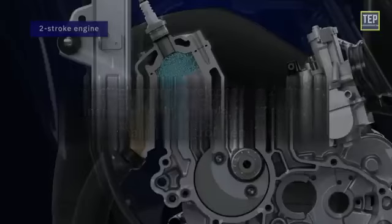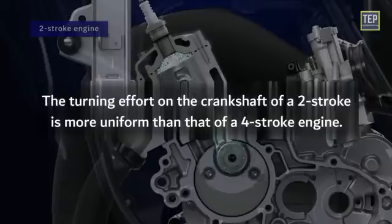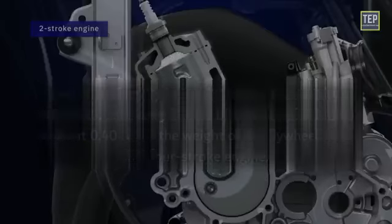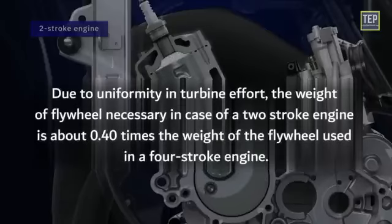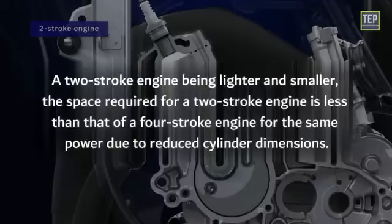The turning effort on the crankshaft of a two-stroke is more uniform than that of a four-stroke. Due to uniformity in turning effort, a lighter flywheel is necessary in the case of a two-stroke. It is about 0.40 times the weight of the flywheel used in a four-stroke engine. A two-stroke engine is lighter and smaller, and takes less space than a four-stroke engine for the same power due to reduced cylinder dimensions.